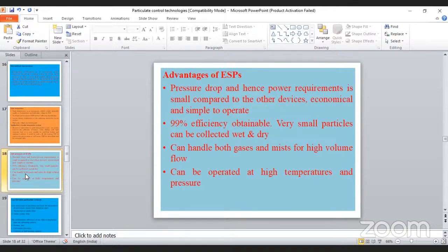After giving the power supply, ionization starts. When the ionization is over, then you pass your impure gas. Then the attraction and repulsion I mentioned takes place, the particles become inactive, and they settle down at the bottom. This process is done in both the intermittent and pulse ionization concepts. When we do it like this, the power consumption for that particular unit is less compared to the other types of operation.